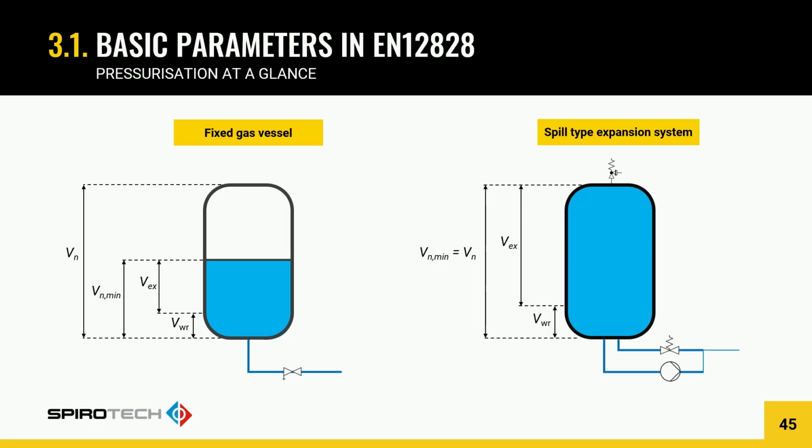In a pumped or spill type vessel, the pressure in the vessel is atmospheric or pressureless. So almost the full tank volume is usable. You don't need to compress any gas. Bottom line, for the same expansion volume, the pump tank can be significantly smaller, and when the pressures go high, this really becomes very significant.